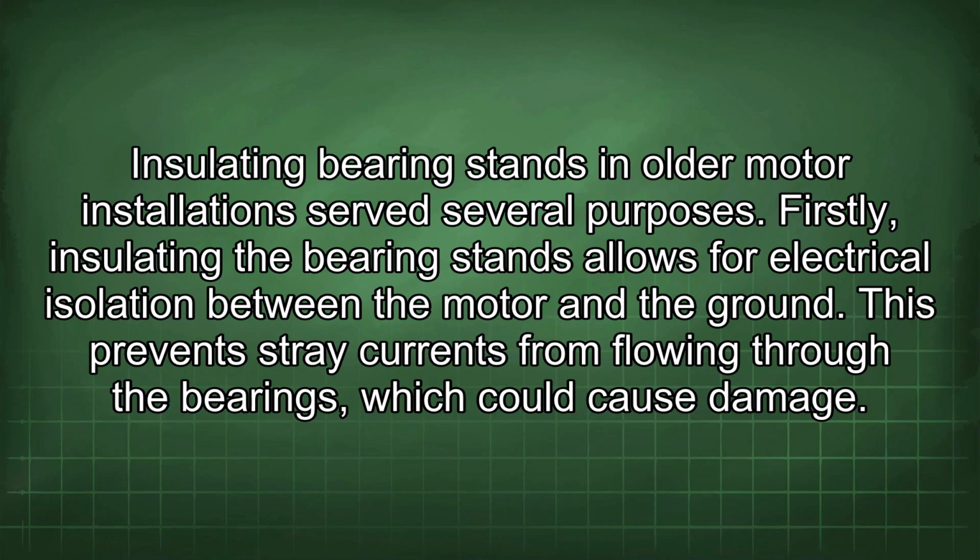Insulating bearing stands in older motor installations served several purposes. Firstly, insulating the bearing stands allows for electrical isolation between the motor and the ground. This prevents stray currents from flowing through the bearings, which could cause damage.